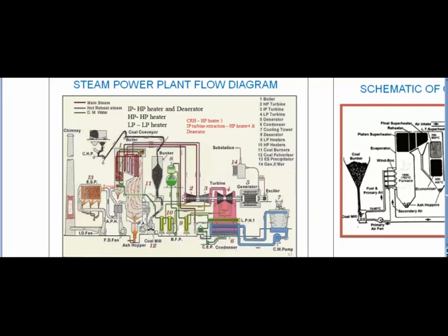The wall of the furnace is made up of water wall tubes. The heat released by the combustion of coal is absorbed by the water wall tubings. Feed water is supplied through the downcomers and bottom ring headers to water wall tubes by which this furnace wall is constructed.